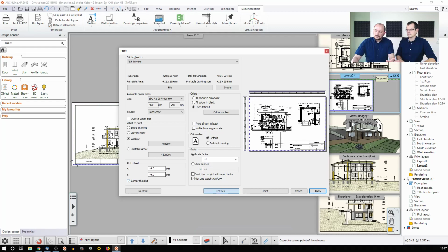So now it's represented this way, and then I'm happy with that. I can center this content. I can fine tune how it's positioned here. And one important thing to highlight here is that the scale factor for a plot layout is always 1:1. You should not further downscale it, because it's already scaled. All the content is already scaled, so you should not further downscale or upscale them. It's just as they are, 1:1. And then just print it, and the software will create the file.